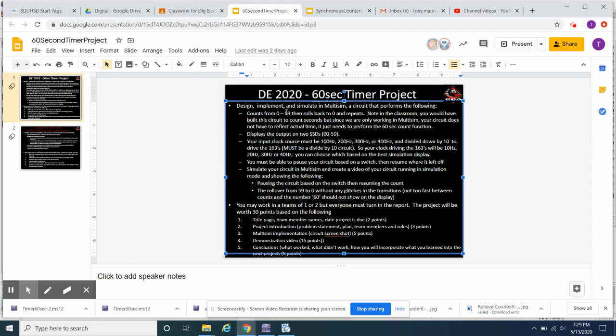The thing that you basically want to be able to do is have your tens digit, right? The most significant digit, that has to only count from 0 to 5 and then roll back over to 0, right? So you have a way of doing that. We know that we can detect the output to be any number, right? We just have to have the logic in there that would detect the 5, in this case 0, 1, 0, 1, right? That's 5. And then we need the other one to detect the 9, right? Which is for the ones digit. So we want this thing to go from 0 to 9, and then the tens digit to go from 0 to 5. Okay. All right.